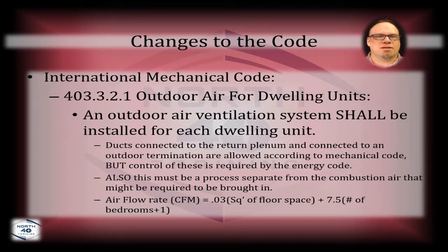Now why? Think to yourself, why would they not accept something that's been used for so long? Well, when we used to recommend that and actually do that, primarily on new construction, we did that for homes not recommending that they run their fan all the time, right? It's a genius idea if you're only running the fan with heat and cool. That way it's only bringing in air during the heating and cooling process. So the air being brought in is going right through the system and it's being heated, cooled, dehumidified.